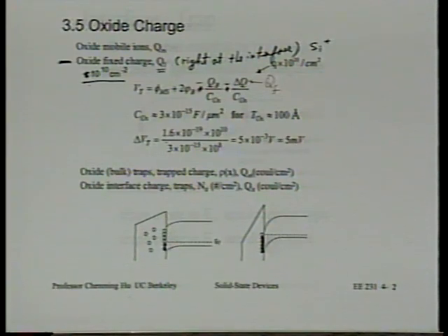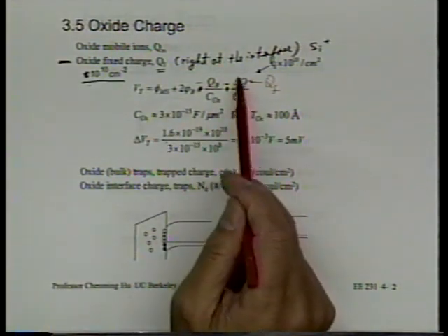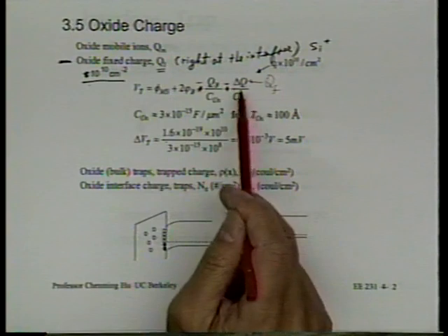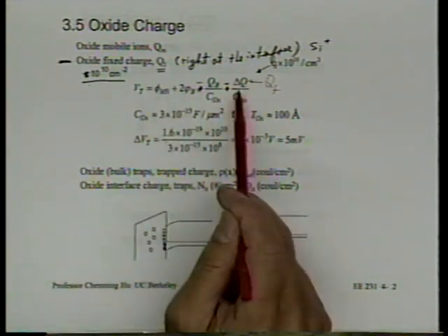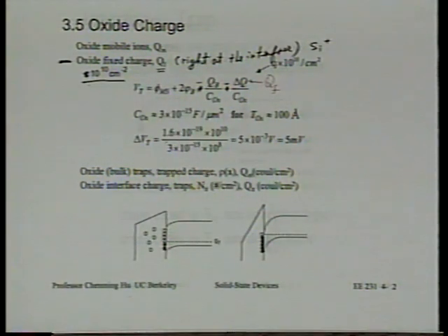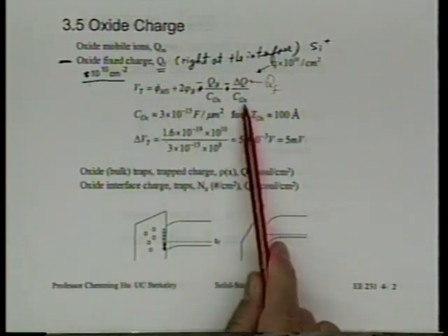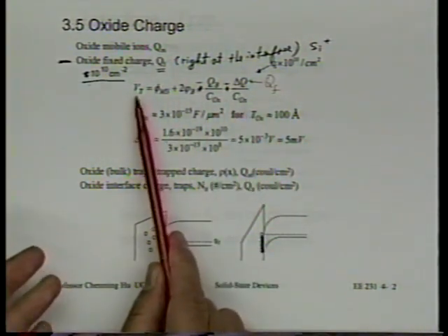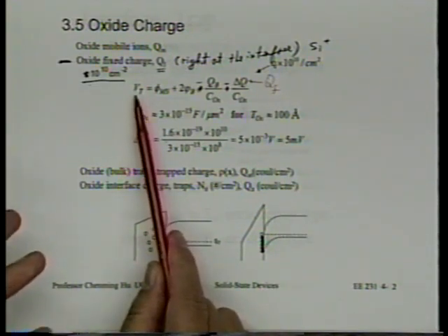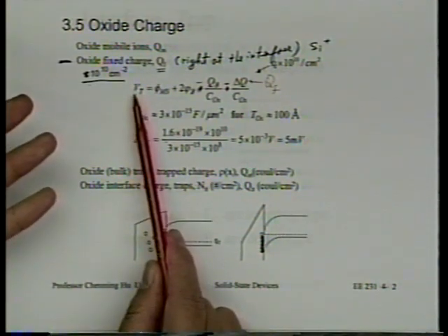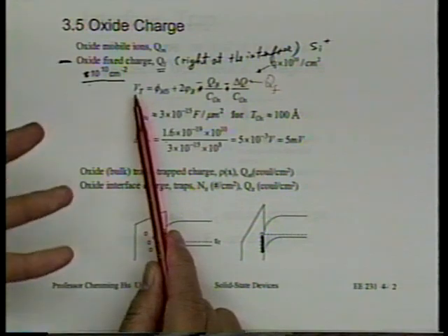Whether you redefine the flat band voltage or not is really not material. But in reality, we do redefine VFB. We would lump this together with that term, put them together and say the sum of these is the new flat band voltage, all right? So flat band voltage does change, and certainly threshold voltage should change very simply from our relationship.